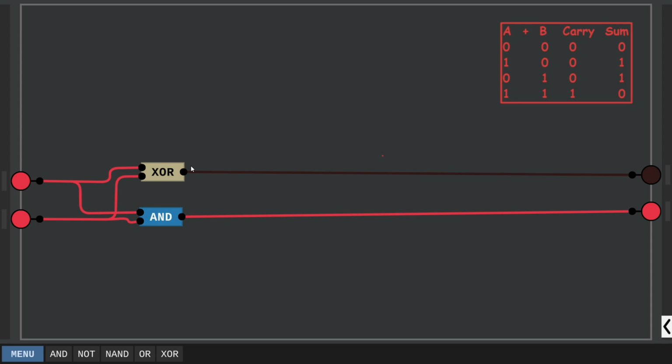As I already told you in the early section of the video, I will connect 1-bit adders to make a 4-bit adder. To do that, we first need to get a carry input. For example, a 1-bit adder will output 1 bit for sum and another bit for carry. Then we will feed that carry into the next 1-bit adder. So here I have added one bit extra for carry, but we have to rewire some of the circuit.